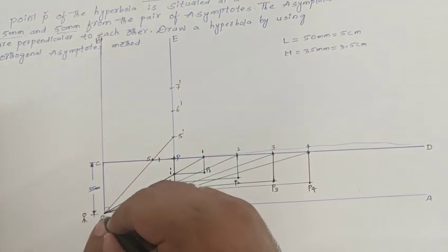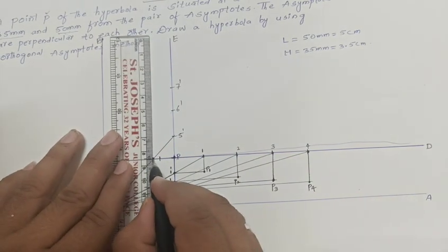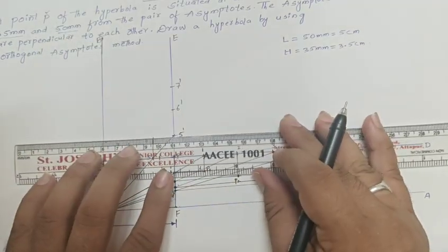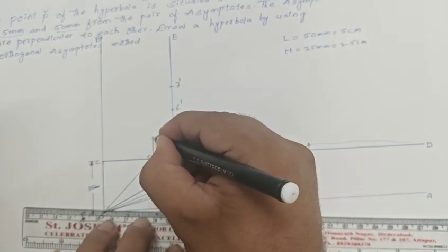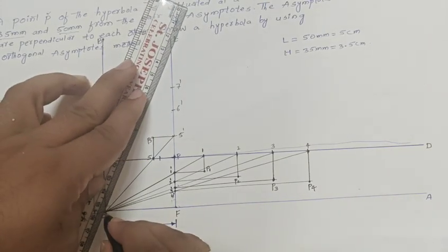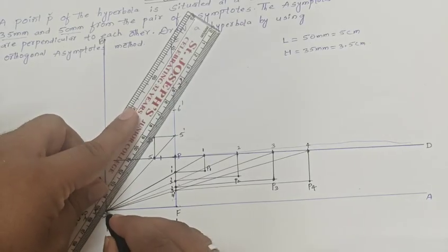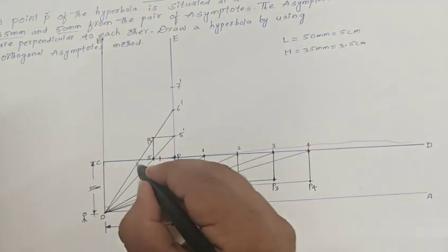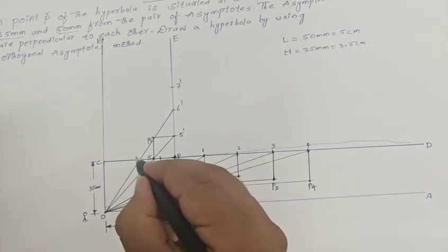There. Again, the observer observes from the origin point. The projection will be passed from origin to 6. Clear? So here, draw the perpendicular line. Same procedure we have to follow. Draw the vertical line and draw the horizontal line. So this point, what we can say here? P5. Same thing we have to continue for 6, 0 to 6. Clear? The projections fall on the horizontal surface. So this is what we can say, 6 point.